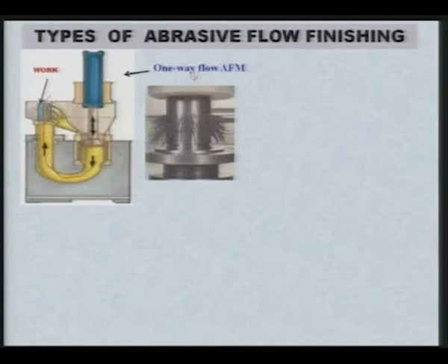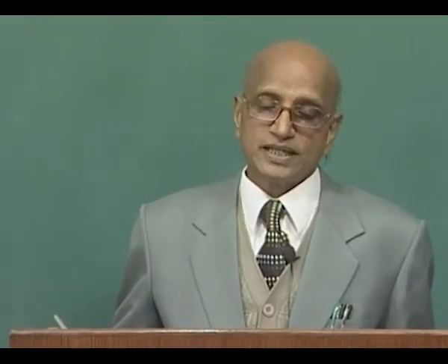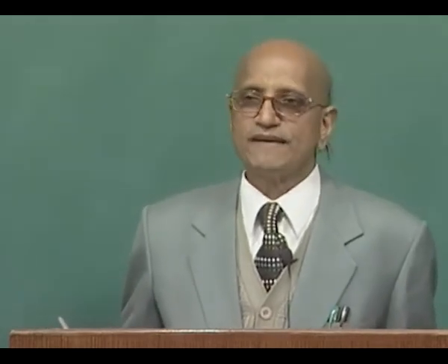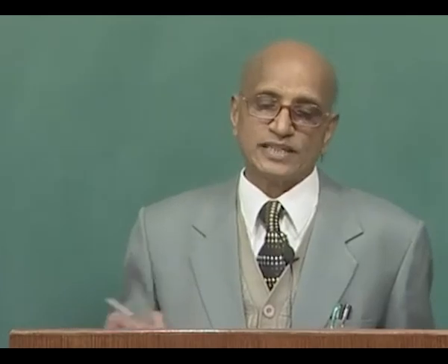So, what happens is that when these abrasive particles come in contact with those peaks of the surface, they are sheared off and you get a much better surface finish in the miniature holes, and there are hundreds or thousands of them. You cannot finish them by any other process except abrasive flow finishing or magnetorheological abrasive flow finishing, because MAF also cannot be applied, because those are solid particles and they cannot easily pass, and you cannot apply the forces the way it is possible with the nature of this type of medium.